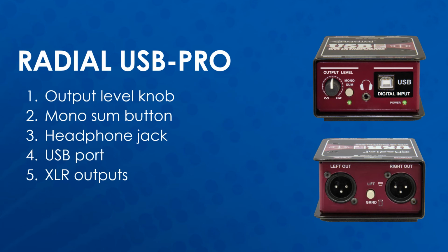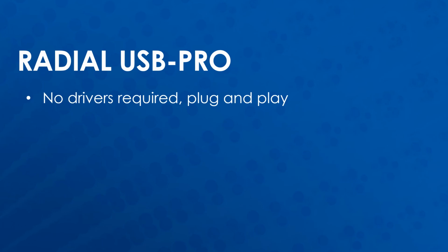There's also a ground lift button. This button can be pushed in if a hum is present in the audio signal. This button lifts the signal ground, which should get rid of the hum. To connect the USB-Pro to a computer, just plug it in and it will set itself up as an audio device. No driver installation is required.